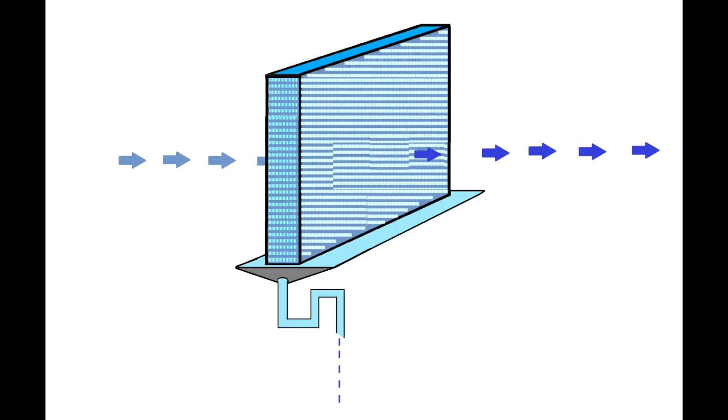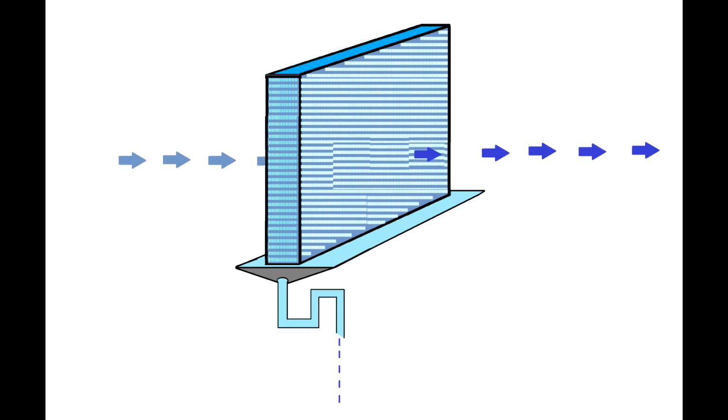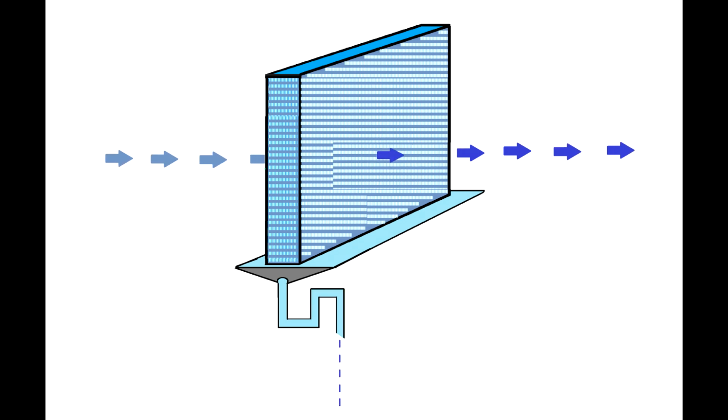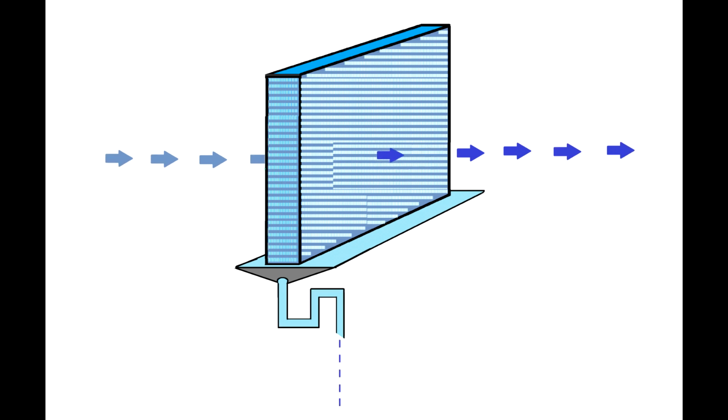All I try to achieve here is just to put some sensors and to control the humidity ratio. So coming back to this story, you see the air is passing by the heat exchanger and will drop the humidity after the heat exchanger through condensation, and the water is eliminated via the drain pipe. You can see it.